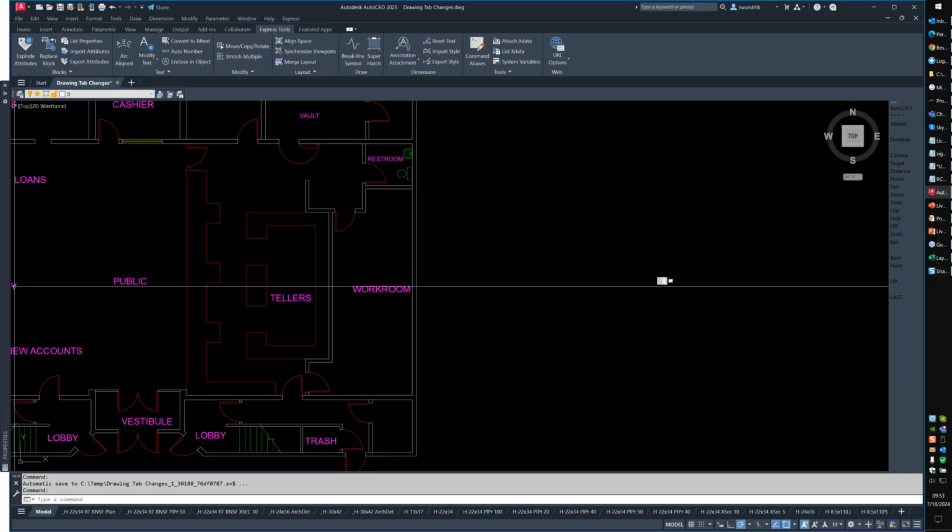What's the difference between DVIEW twist and UCS 3-point rotation? All the twist is doing is twisting everything around the Z axis. So it's only moving X and Y, where with the UCS 3-point rotation, you can alter the Z. DVIEW twist is the old school, only rotates X and Y around the Z axis. With 3-point, you can actually alter the Z. That's the difference there. You guys have had a lot of great questions today. I really do appreciate it.